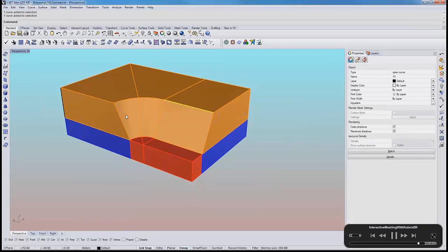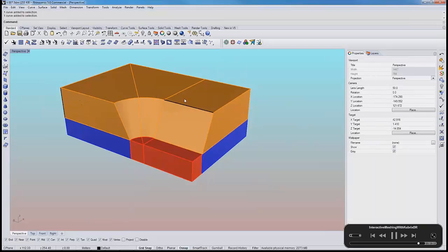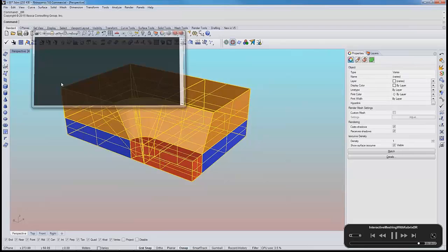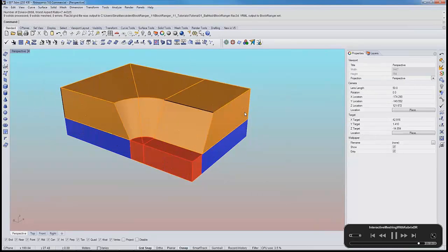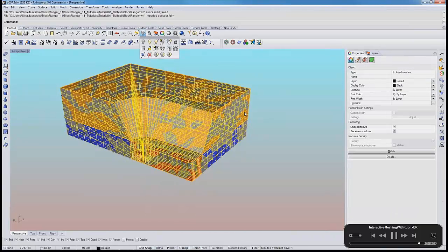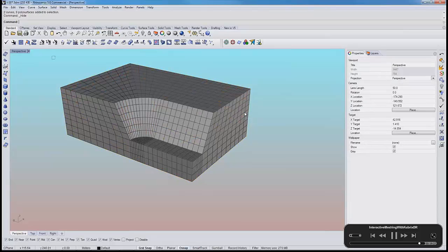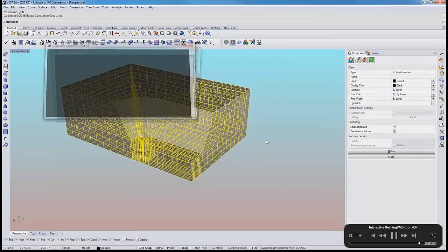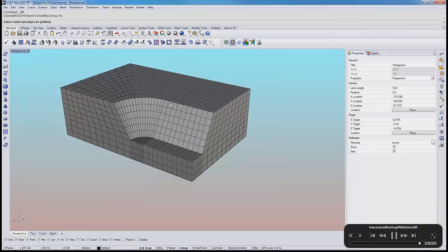when I generate my mesh, you can see there are now 2 edges that have been specified. I select the entire thing, not only the solids as we used to do, but also the edges that now bear the resolution that needs to be handled. And you can see, as the mesh is produced and colorized again, that the new mesh complies with the resolution that we wanted.